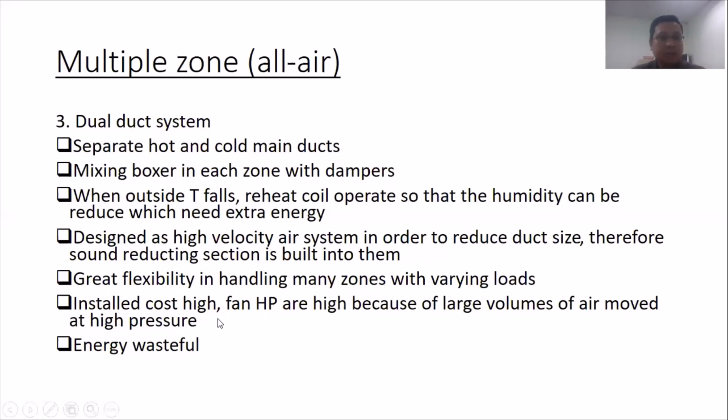Then install cost is high, and fan horsepower is high because of the large volume of air moved at high pressure. So if we install one set for multiple zones, we also have to invest in much more equipment, especially the fan to supply the air to every zone. And then energy is wasted, so it's not efficient.